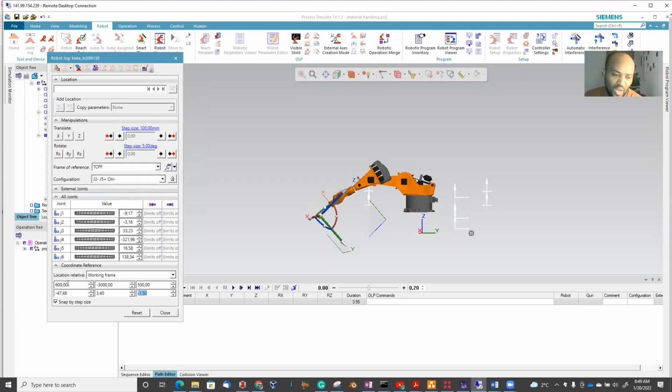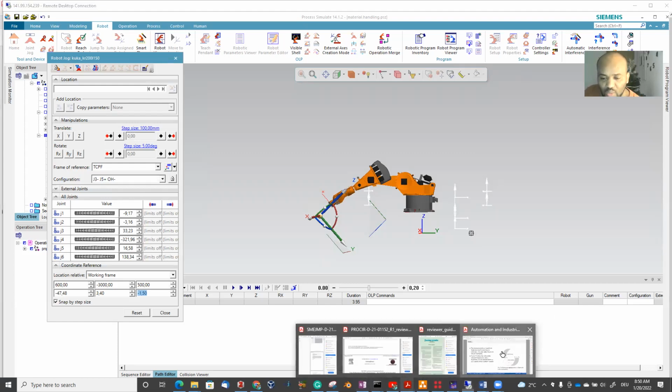So what does that mean? When we have forward kinematics, you know theta, but you don't know the px, py, pz, the position vector. When you have inverse kinematics, or indirect kinematics, or reverse kinematics, you know the operational space information, which we call px, py, pz, and rx, ry, rz. And then you get theta 1, theta 2, theta 3, theta 4, theta 5, theta 6. So that's why we have forward and inverse kinematics. And you have to know this. Okay, so that is one point.